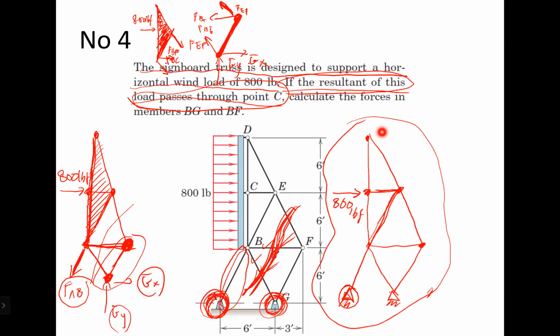Okay. So at point A, we can change the AX and AY to be FAB, right, sir, to make it easier? No, we don't have to find AX and AY, because at point A, the reaction force, like it or not, must be in the direction of FAB.